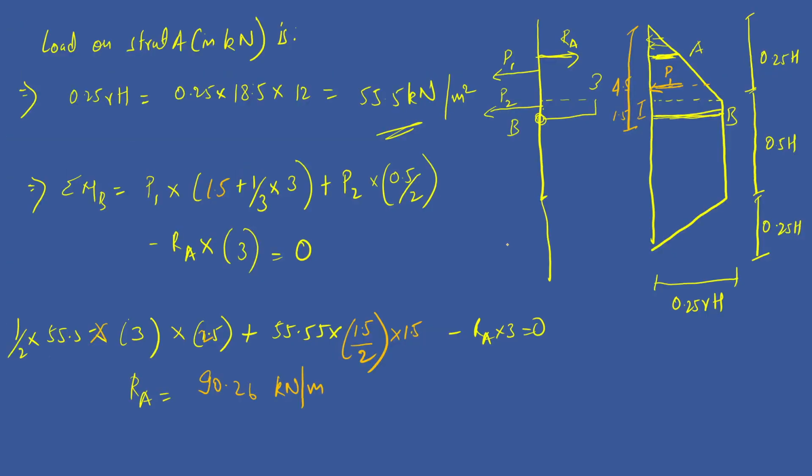Then you have to multiply. This is acting at a single line. If we see the location of the struts in the longitudinal direction, meaning into the page, then longitudinally also you have the placement of the struts. So for getting the force in each strut you need to multiply this value with the spacing, the horizontal reaction spacing.